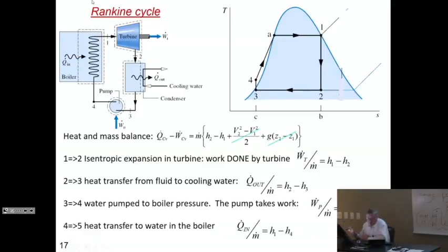So in these cycles, in fact, just like we did when we introduced cycles, the numbers are all going to be positive, and we are going to change the signs in the energy conservation equation. So the signs are going to be determined by the direction of the arrows for work out, for heat out, for work in, and for heat in. Always have your schematic diagram, always write your arrows so we know which signs we're going to be using. But by convention in Chapter 8, these signs will be all positive. And that's it for today.